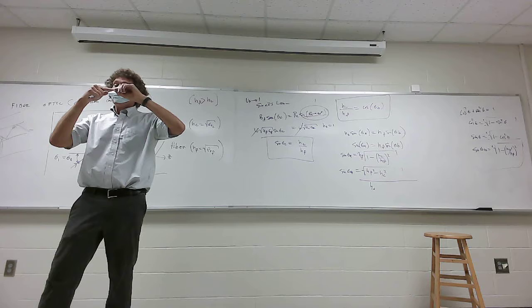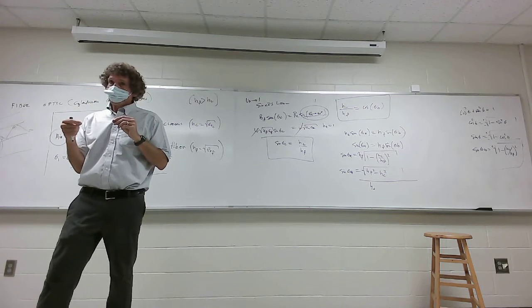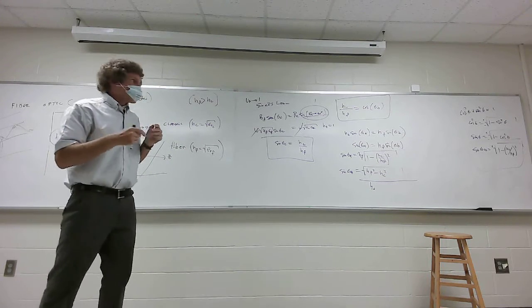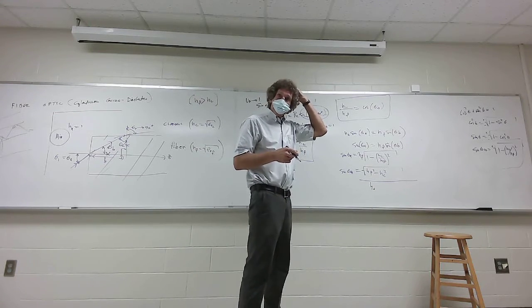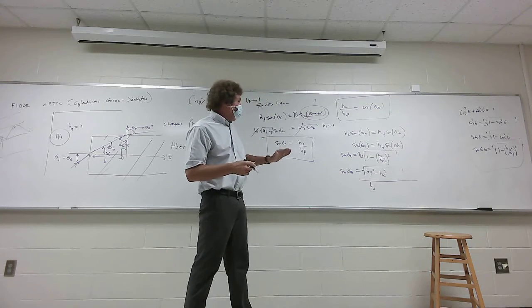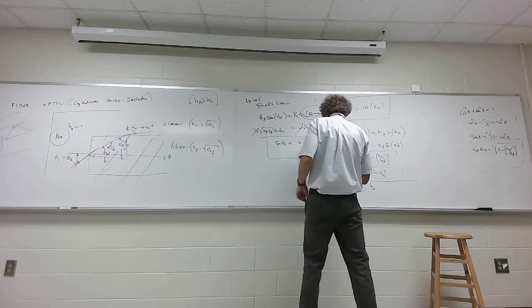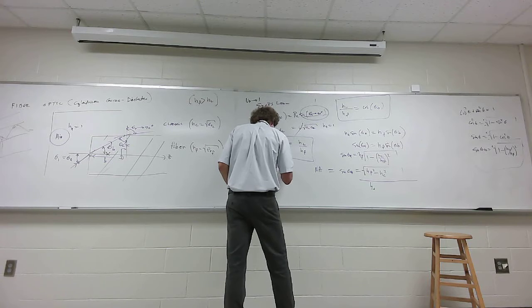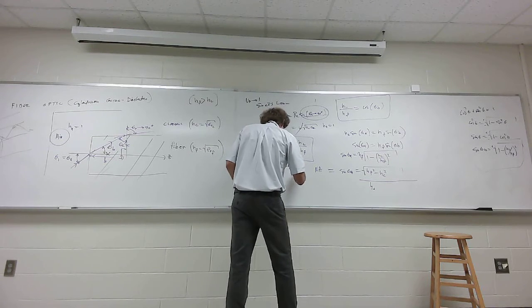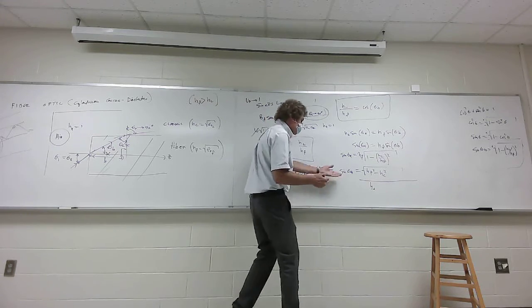So if you have something where there's a little bit of wiggle room here and it's in an area with a lot of vibrations, then it will not work. Y'all follow me? So it's real important for alignment. So what they do in fiber optics is this. They assign a figure of merit to how close you have to be to this angle. They call this the numerical aperture. This is called NA. It's in your book. It's just the sine of that angle.